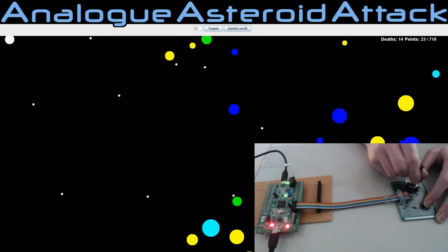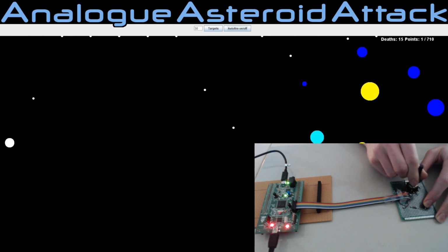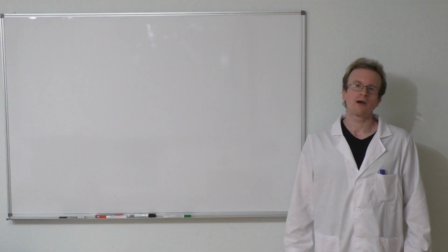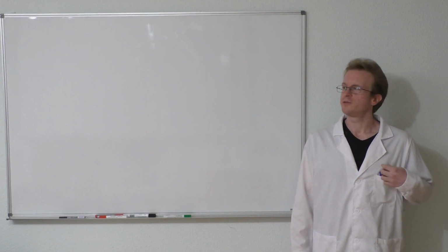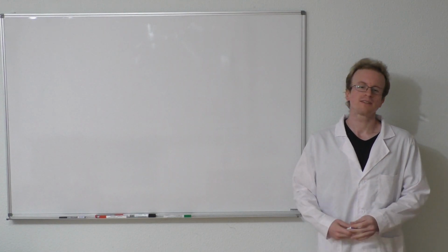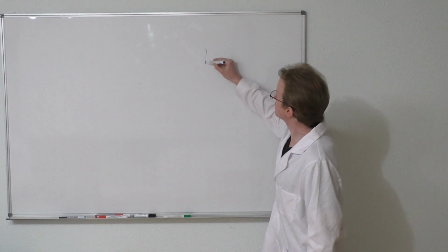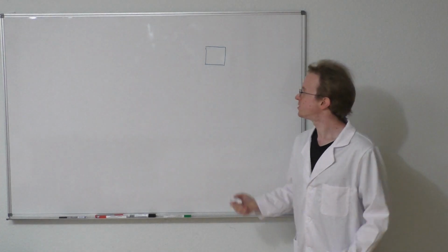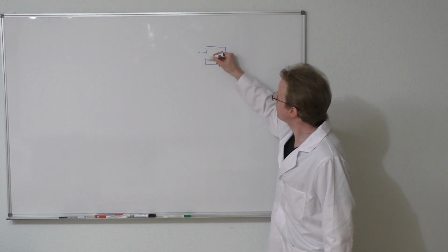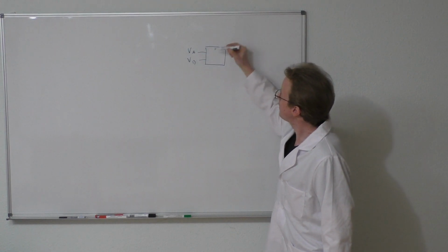As mentioned, I'd like to conclude this video with a small insight into the internals of an ADC. Let me give you a rough idea how analog-digital conversion works. There are several approaches in practice to do this. One of the easiest ones to understand is using analog comparators. An analog comparator is a building part that compares analog voltages. So it has two inputs, voltage VA and VB.